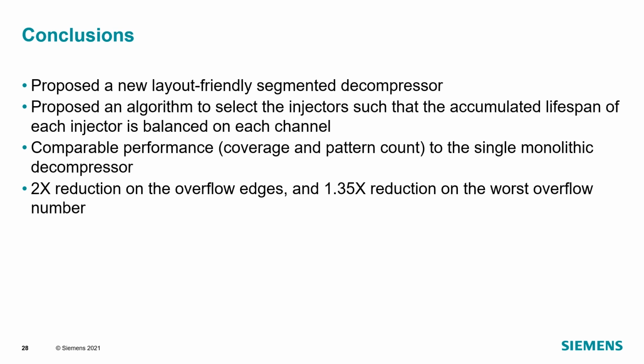Since the input channels are distributed to the segments, the new decompressor has comparable performance, coverage, and pattern count to a single monolithic decompressor. Finally, there is a significant improvement in key layout metrics: 2x reduction of the overflow edges and 1.35 reduction of the worst overflow number.